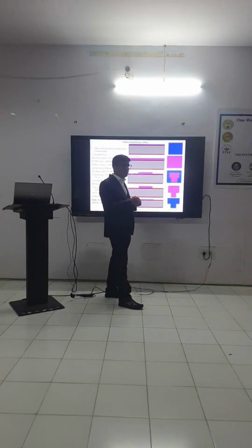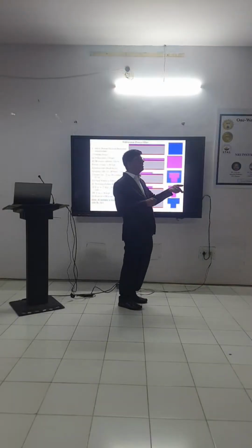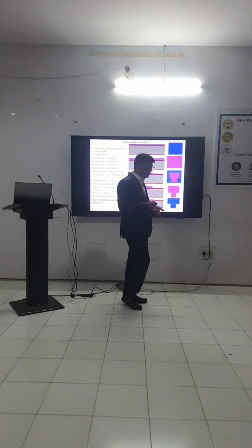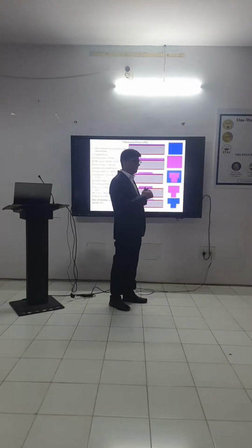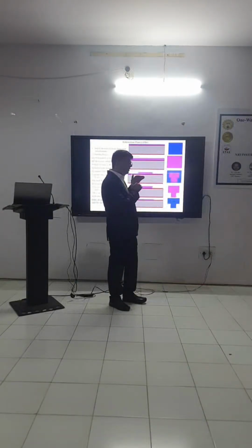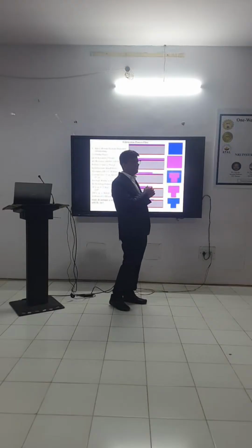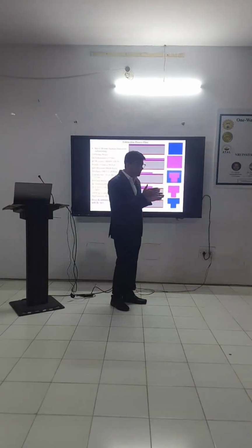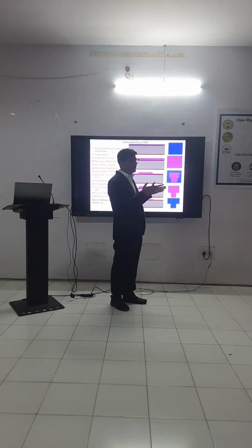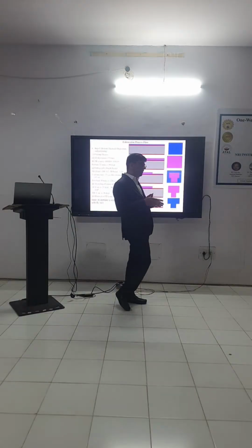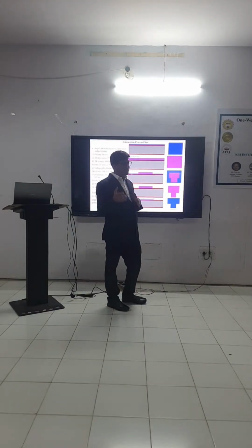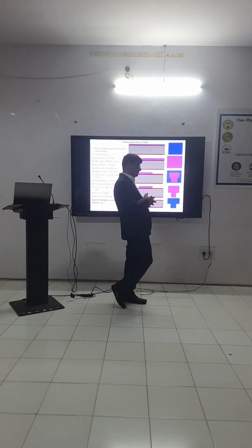Okay. But the problem with this mirror is that you can't strictly control the thickness of each mirror layer, because we have to strictly control the thickness of the mirror layer. If you do not control it, then what will happen? It will shift your frequency. So it is okay if you are going for a sensor. But if you are going for designing a filter, then you will not get the performance you are expecting. Okay?